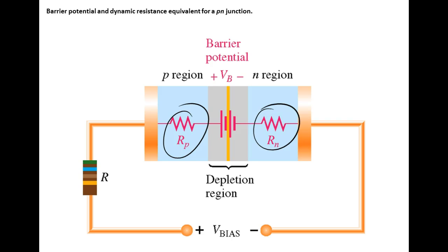I think this diode right here is a 1 amp diode, and the maximum VF would be 1.1 volts, which is less than 400 millivolts over the 0.7 of a volt, and that's over its entire range, at 1 amp. If you run over 1 amp, you could burn the thing up. Understand?